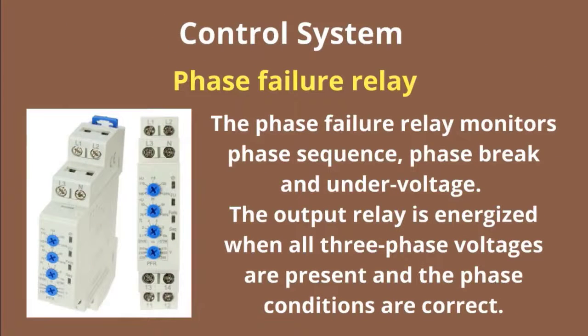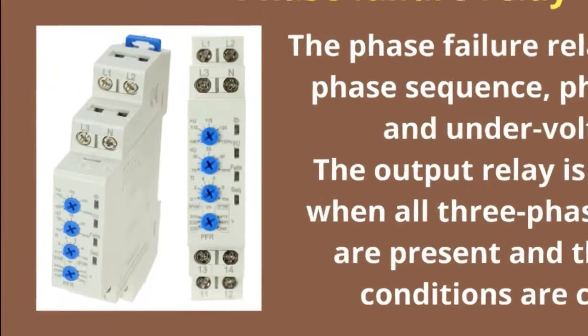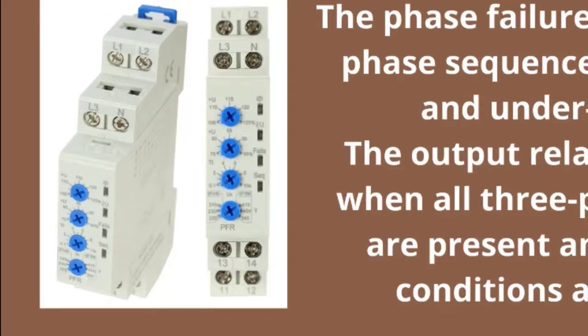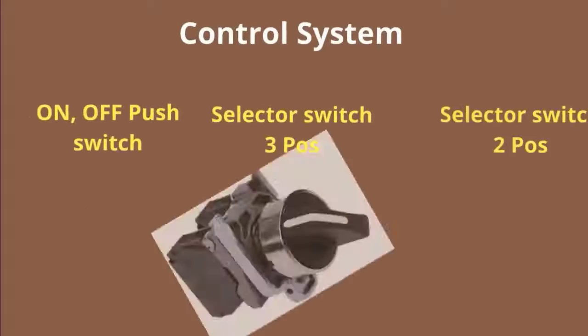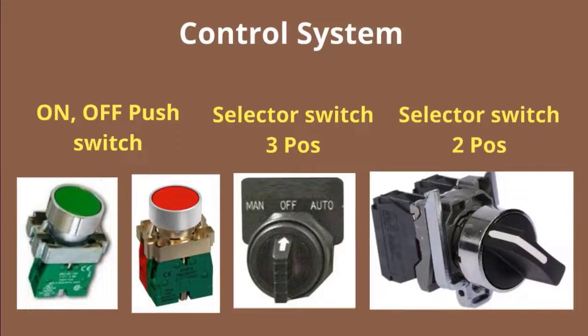Phase failure relay. The phase failure relay monitors phase sequence, phase break and undervoltage. The output relay is energized when all 3 phase voltages are present and the phase conditions are correct. Control switches.